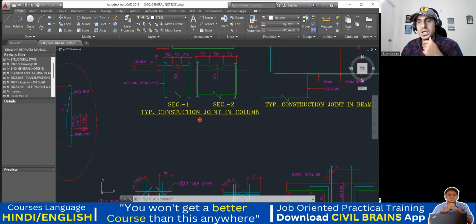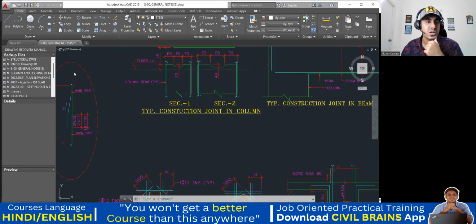Usually what happens when we do the casting of a column, suppose I am casting a column in a building with 3 floors. I'll say this is floor number 1, then floor number 2, then floor number 3. So you will not cast the column in a single go. You'll cast this part on one day, this on another day, and this on another day.